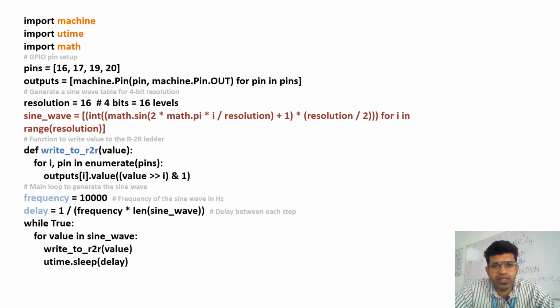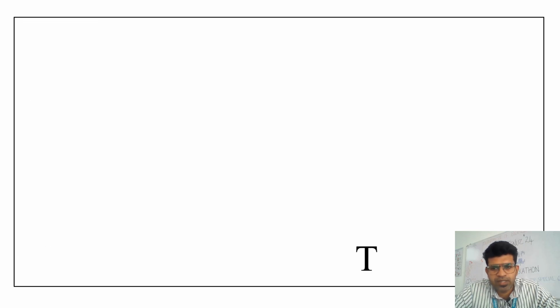But then on paper, it's actually a perfect sine wave. But if you see it in the DSO or other display devices, you can see it's not a proper sine wave because of the 4-bit DAC, right? And added to that, we are using exposed resistors and not proper wires, so all those things contribute to the noise, right?